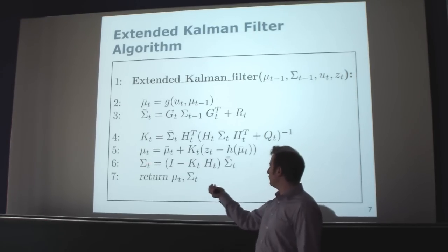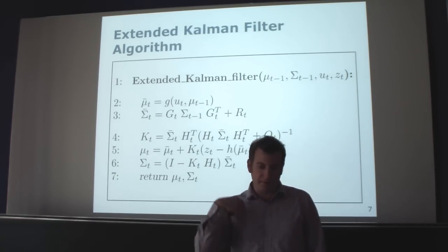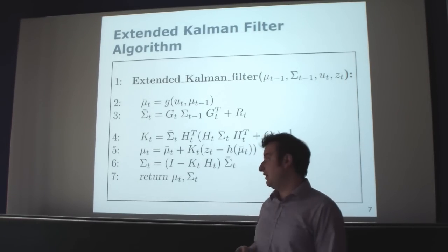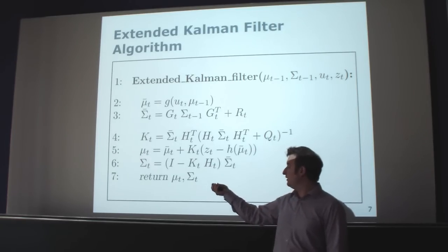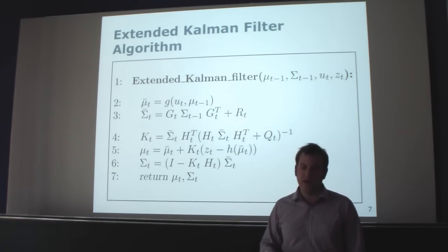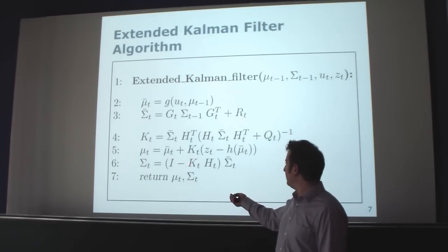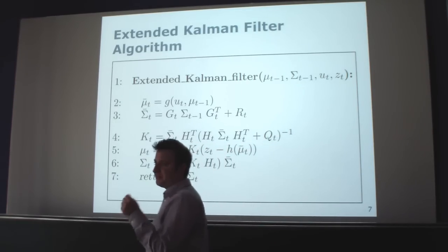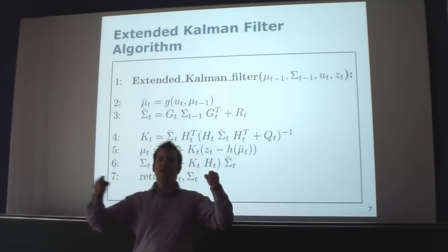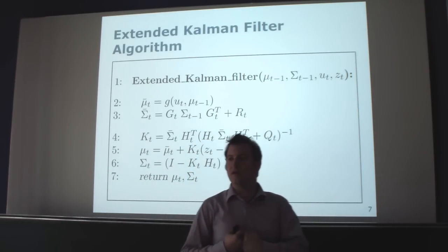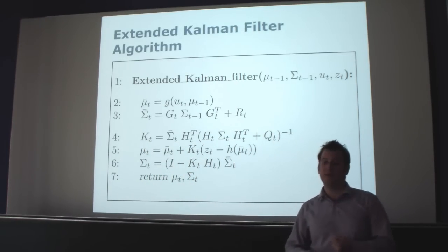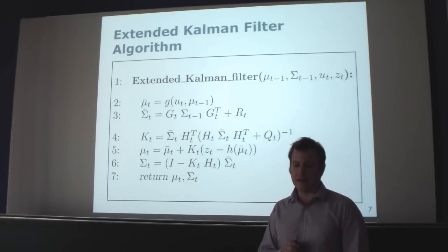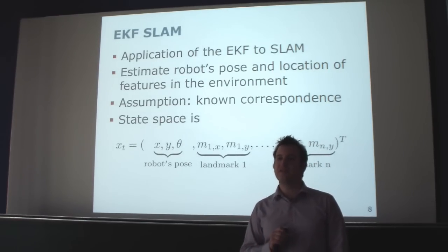And then the second term is the corresponding change of the uncertainty, the covariance matrix, and here the Kalman gain is again involved. So if I trust my observations a lot, the uncertainty typically decreases in the estimate I have here. Okay, so let's look at EKF SLAM.